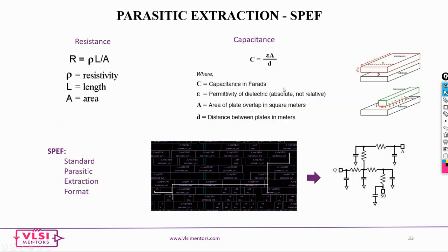And the next step is basically parasitic extraction. Now imagine any wire that you have, this physical wire. It can be modeled like an R and C, correct? So it's like your R and C. Now the amount of time it takes to reach from here to here is basically your R and C, tau equal to RC, right?